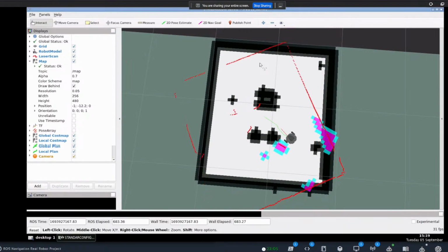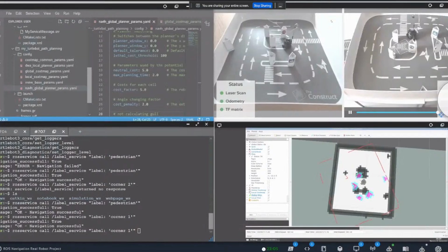So the robot is going forward here, and it won't replan because it's following the plan, right? When it gets to that point, it's like, oh, there are more obstacles, so it's going to replan. You also have a parameter of how many times you want to replan, and if that gets exceeded, you're going to have a navigation not successful.